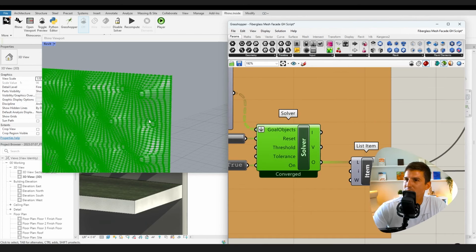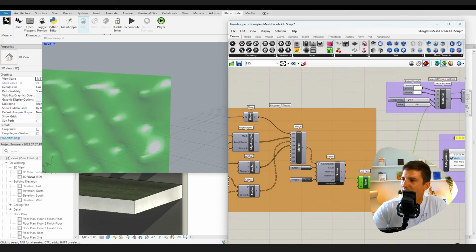And then that'll make sure that the mesh is part of the output. And we just want the first item on the list, which means it's going to take, based on what it's saying here, what is being output. Notice the first item here says mesh. That's the one we want. So under list item, the default here is just going to be 1, which technically is list item 0 because it starts at 0, then 1, 2, 3, 4. Anyways, essentially we're taking that first mesh item and getting that out.